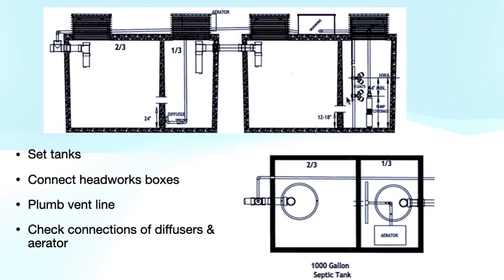The second tank, for everything going to the Oscar, we have here a headworks drawn on top of the tank. In this instance, this headworks, what we call our reverse flush headworks, is required to be on top of the tank for a number of reasons, whether it's thermal protection or ease of the pump lines and where it's going to. We'll get into the specific connections that are going in and out of the headworks at a later point, but that's the location of the headworks, directly on top of that second tank.